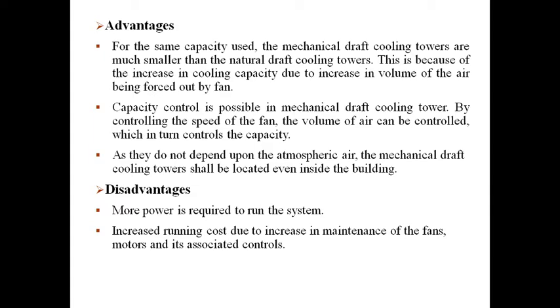Are you clear? Okay. So the limitations of mechanical draft cooling tower: more power is required to run the system, because more mechanical devices are also used here, like fan or blower or any other devices like fill, then motors. So due to this, more power is required to run the system. The running cost also increases because of increase in maintenance of the external devices like fan or motor and its associated control. Are you clear?